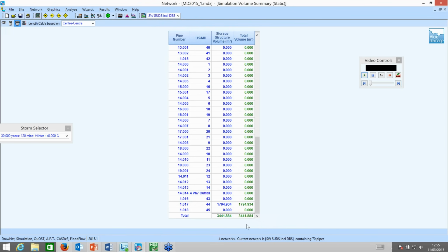In this case, you've just got the one structure right at the bottom there, as well as our deep bore. So it's essentially telling me at manhole number 1, we're gaining 14.577 cubic meters of volume in that 25 meter deep borehole.